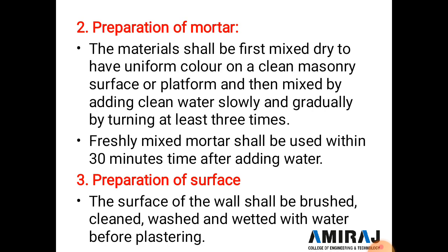The second specification for plasterwork is the preparation of mortar. The materials shall first be mixed dry to get a uniform color on a clean masonry surface or platform, and then mixed by adding clean water slowly and gradually, turning at least 3 times. The freshly mixed mortar shall be used within 30 minutes after adding the water.